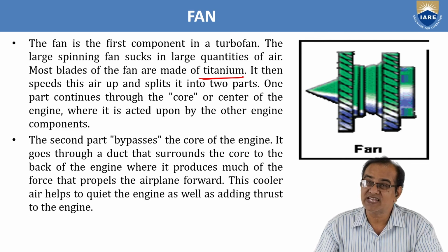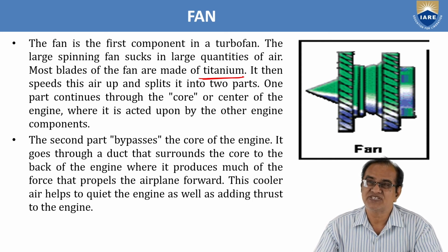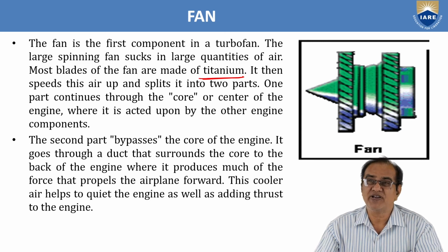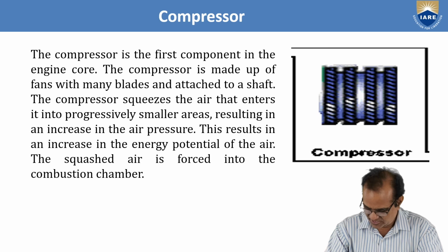So this bypass has 2 benefits. The sound is reduced, the noise of this turbofan aircraft engine is reduced, and also it is not taking part in burning, so the efficiency of the engine is increased and thrust is also increased. So that is the benefit of the fan.